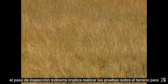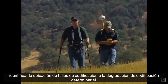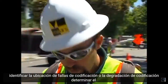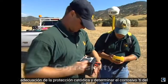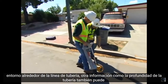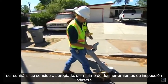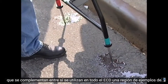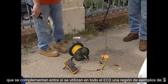The indirect inspection step involves performing the above-ground tests to identify the location of coating flaws or coating degradation, determine the adequacy of cathodic protection, and determine the corrosivity of the environment around the pipeline. Other information, such as pipe depth, may also be gathered if deemed appropriate. A minimum of 2 indirect inspection tools that complement one another are used over the entire ECDA region.